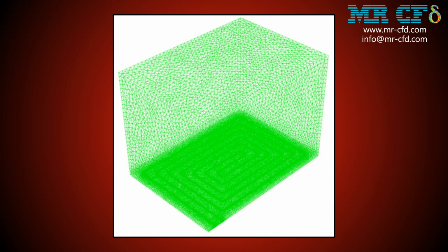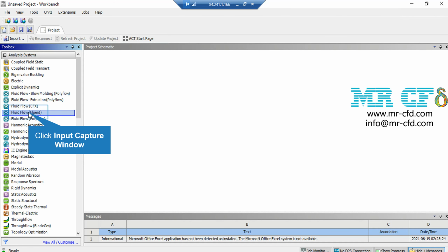The meshing of the present project was carried out using ANSYS meshing software. The mesh type is unstructured and the element number is equal to 2,936,179.